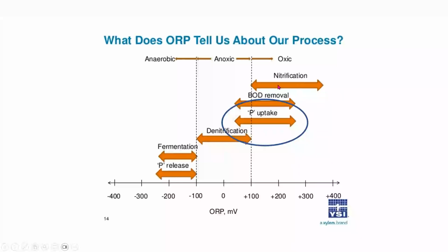So back to that, I really like daily monitoring, field monitoring. I want the numbers today for ammonia at the plant. If you're doing in-house ammonia testing of the effluent and you're seeing low ammonia numbers, the only way you're getting there is by getting the BOD out of the way to get ammonia removal and creating an environment that's also good enough to support phosphorus removal, with a couple of exceptions, a couple of nuances. And I'll drive those home during the course of this discussion.